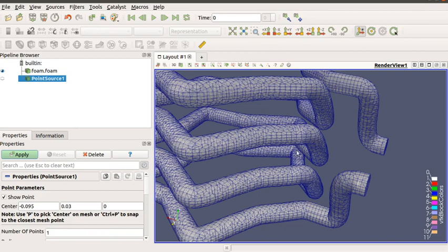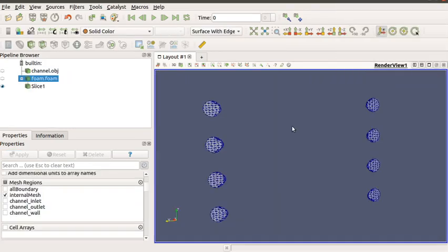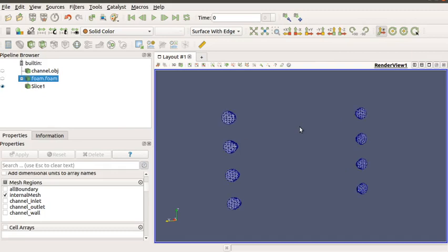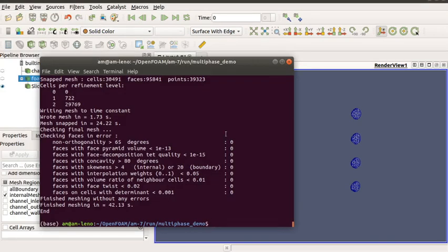Okay, the next step is setting the field. So we have successfully created a snappyHexMesh. Next the command will be setFields, to set the field alpha.water value equal to 1. For that I am going to type setFields with capital F. I am entering that.